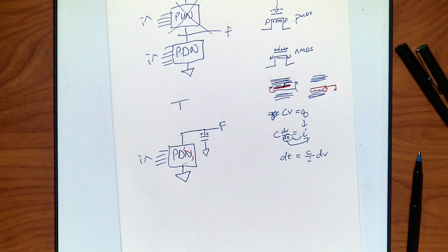What does it take to charge a capacitor? It takes voltage, and some time. So I have to have a charge period and a discharge period. Does that make sense? Okay, so since I now have two periods, do we have any type of timing thing that has two values? Regular intervals. A clock. It's got a high value, low value, and it alternates, and we can make it as fast as we want.